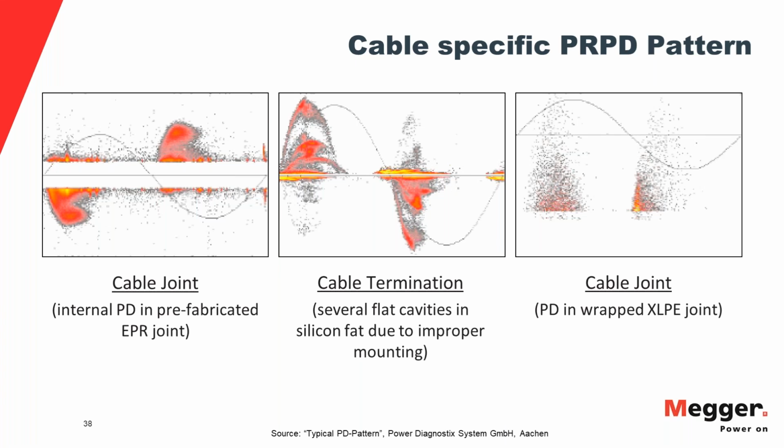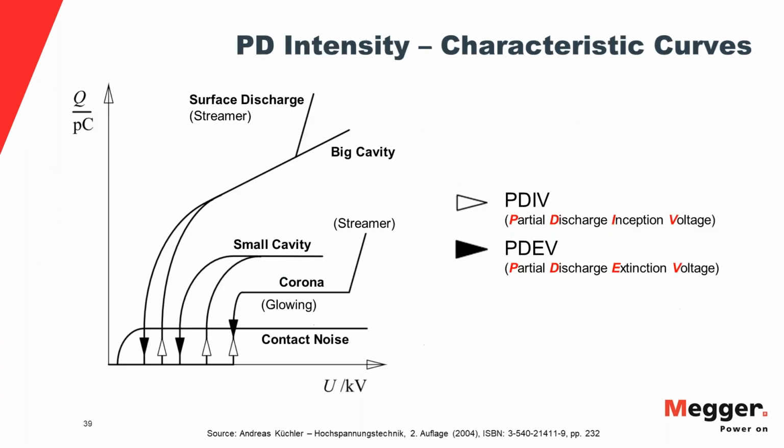On other assets, let's say motors and generators, it's very useful because there the device is built in a way that the traveling wave method is useless in a generator winding or something. But the phase resolved patterns will tell you a lot about where it happens, end winding or somewhere else in the stator or on the rotor, whatever you're testing. And so the phase resolved patterns in the motor testing business have a very good application there.